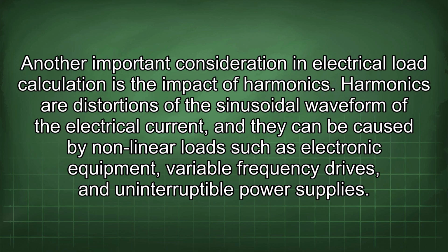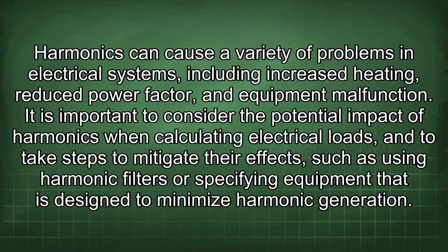Another important consideration in electrical load calculation is the impact of harmonics. Harmonics are distortions of the sinusoidal waveform of the electrical current, and they can be caused by nonlinear loads such as electronic equipment, variable frequency drives, and uninterruptible power supplies. Harmonics can cause a variety of problems in electrical systems, including increased heating, reduced power factor, and equipment malfunction. It is important to consider the potential impact of harmonics when calculating electrical loads, and to take steps to mitigate their effects, such as using harmonic filters or specifying equipment that is designed to minimize harmonic generation.